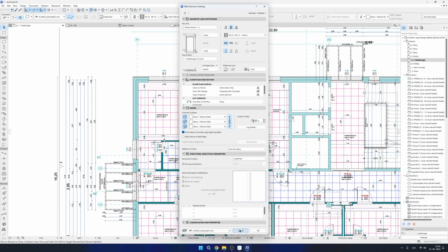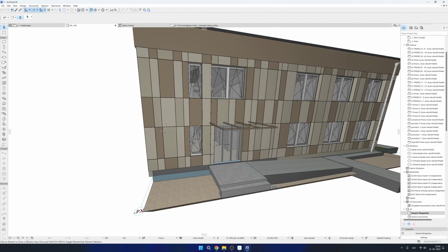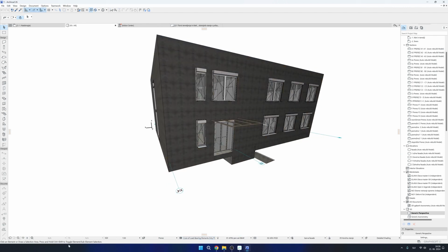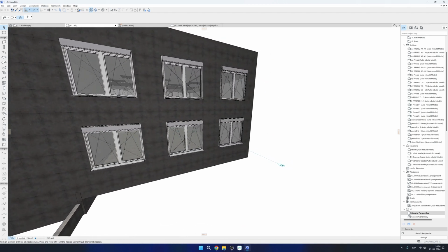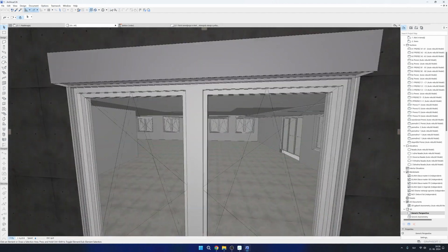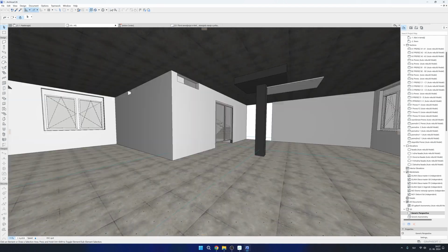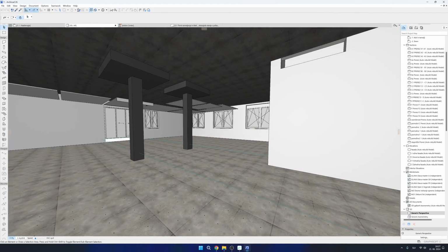When we have everything defined, let's go to the 3D model, and we can use this view. So now we are viewing the entire model. Let's just view the core of load-bearing elements only. If I click this, I'll now only see the load-bearing elements. So if I go inside the building, I don't have any more of these dividing walls. I just have the RC elements.